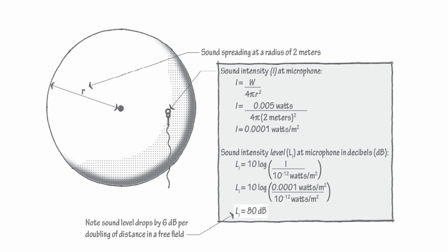And also, there is one common misunderstanding. You have a sound pressure level of 81 and a sound pressure level of 80. These are not a linear difference. It's more of a logarithmic difference, so there's a difference in exponent level. It's a larger difference when you say one source is 80 and the other source is 81. You have to keep that in mind.